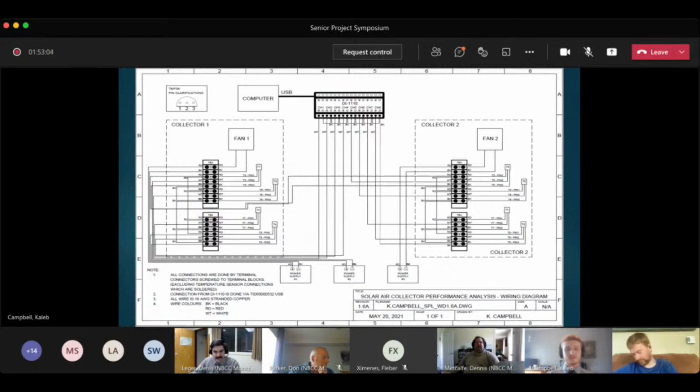I'll tell you one thing that I do appreciate, and maybe you should have considered that, is to use kind of the bus topology for this, using bus techniques, where you would have had, and you do have, the color codes on the end there near the TB3, TB4, and so on, and you can identify them on the other side in the same manner. Right, so that would have helped you a lot too. Maybe using common busing symbols in between there. But anyway, I'm not here to correct your drawing or anything. Just I noticed that once again, just seeing it this time around, I was like, why did that?